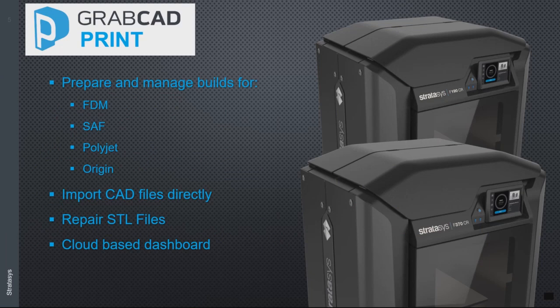So you can drag and drop SolidWorks files or Pro-E files or any type of the more common CAD softwares. You can just drag your files directly into GrabCAD Print and print directly off of those. It can also do STL file repair, so you don't need to have a separate software for that. And GrabCAD is also a cloud-enabled software, so it can actually report printer data to a cloud server, and you can view that data. You can see the printer statuses, you can see the printer schedules, you can see printer histories, and also some reports based off those histories in the web app.